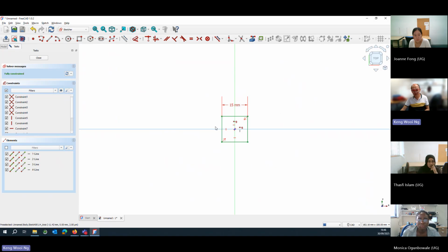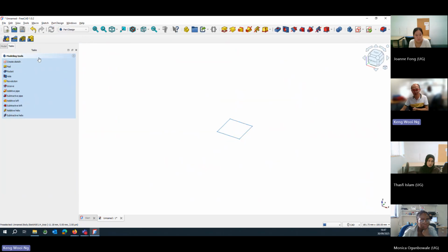What it doesn't have is thickness, right? Now you're still in the Sketcher workbench. Whenever you have these kinds of items show up on the left-hand side, you are in a specific function. These parameters and this information are specific to the sketch function. So you need to exit this function first, close. Whenever there's a close function, close it when you're done.